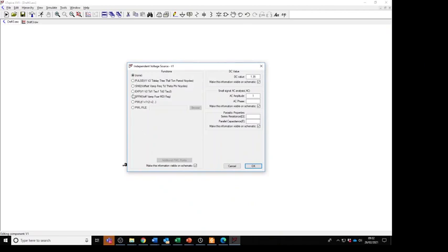So let's do something. Let's change this into a sine wave source. We're allowed to put a DC offset on. We need that at the moment for our bias. And then we're going to put in an AC signal. Let's put in an AC signal whose amplitude is, what should we say, 100 millivolts, and let's give it a frequency of 1 kilohertz.